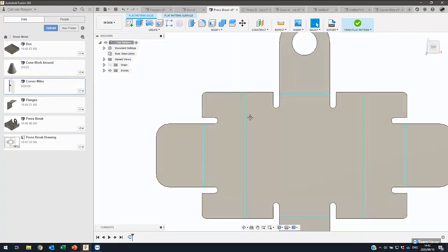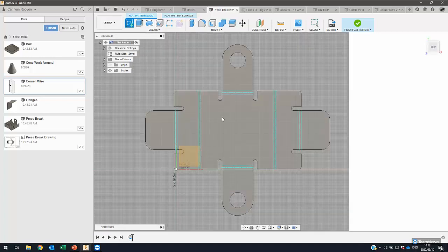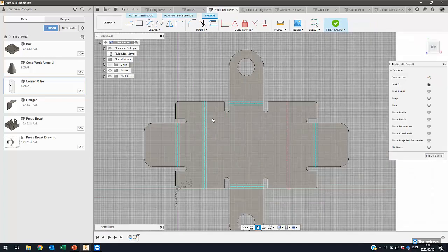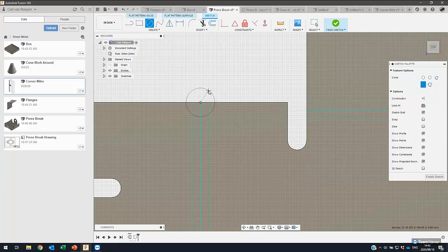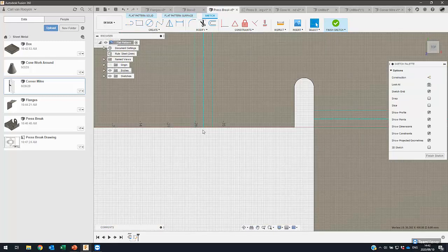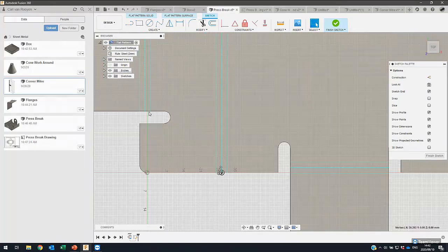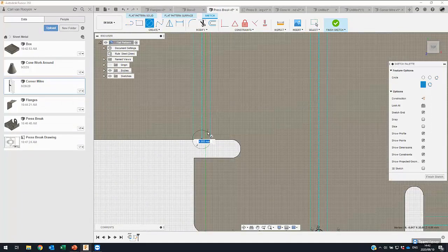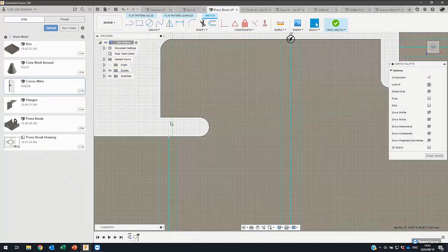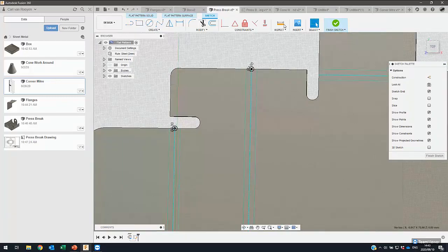It is automatically updated to show the changes, and from here within the flat pattern environment, you're able to go ahead and, as I mentioned earlier, add features. So from here, I may want to add a couple of notches into the profile to allow the operator who is bending up this component to align it within the press brake. So I'm just drawing a series of 2mm circles.